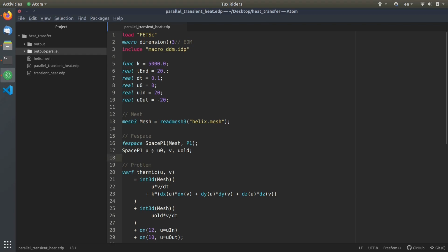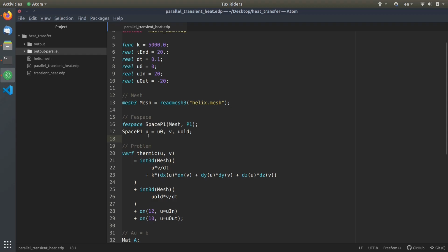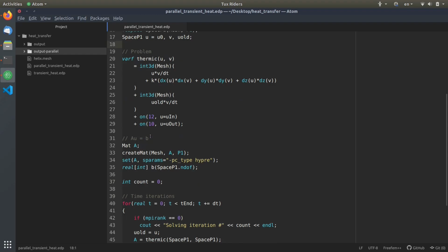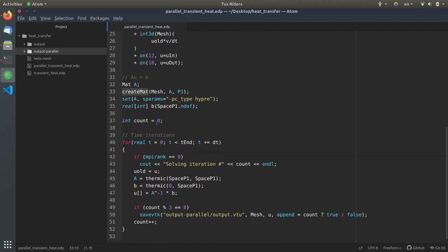I didn't do that because U0 is 0 here, so I thought that maybe that's not a problem, but maybe it is. That U is currently defined on the global mesh, and later on when we decompose the mesh, we never said to map it into the local ones. And later on we use the local things and we just assemble everything in the post-processing software.